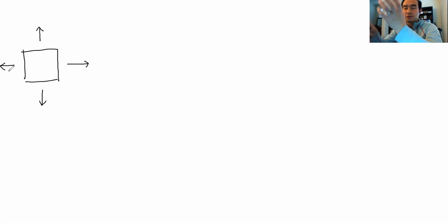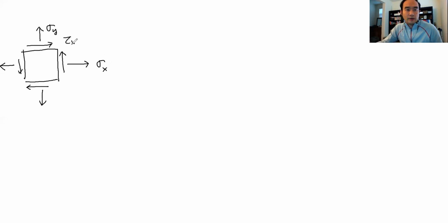The other one, the circular shaft: on the surface, we can say that it's going to be the plane stress condition. When it is considered as a plane stress condition, we can simplify the cube into this two-dimensional plane. So this is going to be sigma x, it's going to be sigma y, and by the way, I'm drawing all stresses in a positive direction right now. So this is going to be tau xy, and tau xy and tau yx will be equal to each other. So we can express any state of stress with these three stresses, sigma x, sigma y, and tau xy.